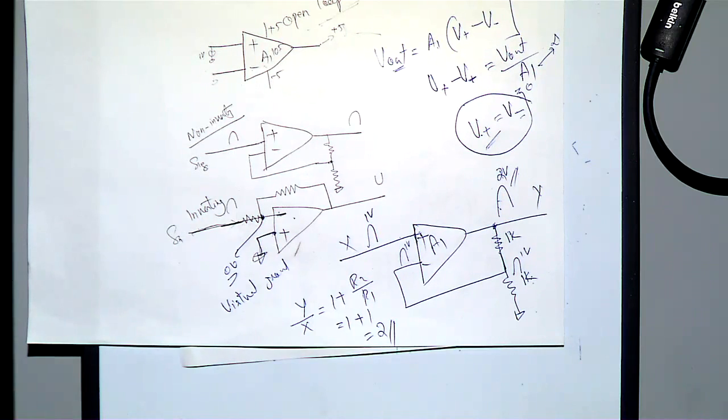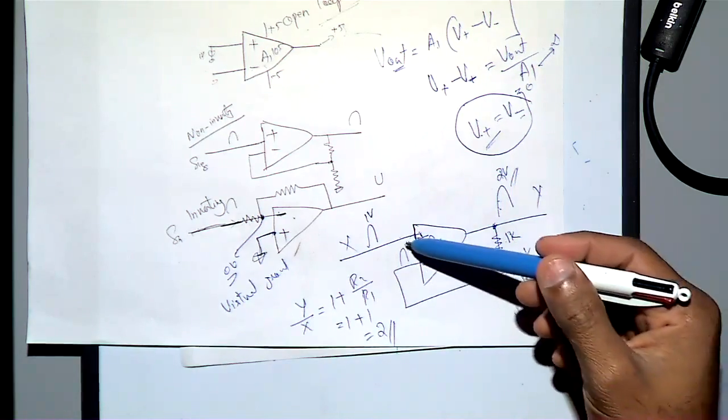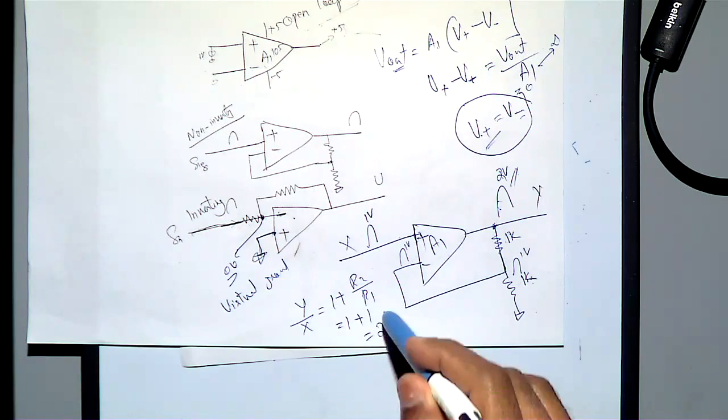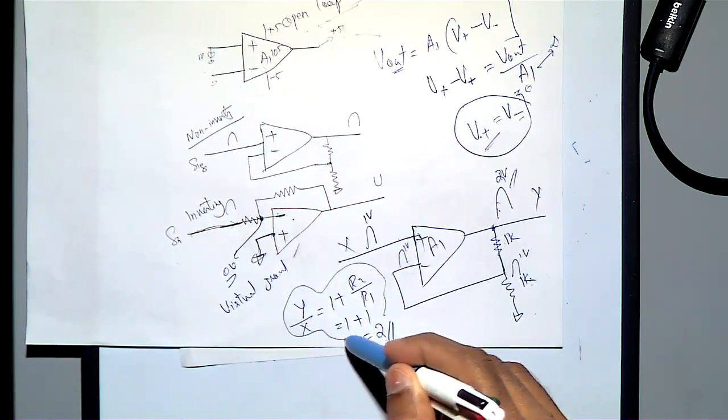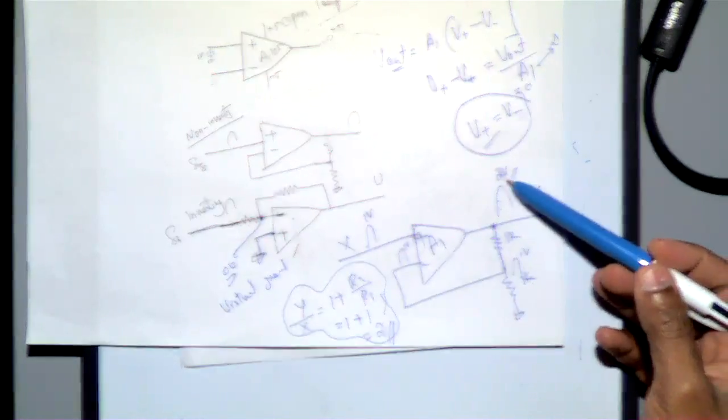So now you don't need the equation. You can conceptually understand. You can find these equations without memorizing, using this virtual ground, you can amplify the signal. You know what I meant? So that is the concept of virtual ground. So using the concept of virtual ground, whatever we discussed, see, this is a gain we derived in the slide, but without this equation, still, we can find out the amplification.